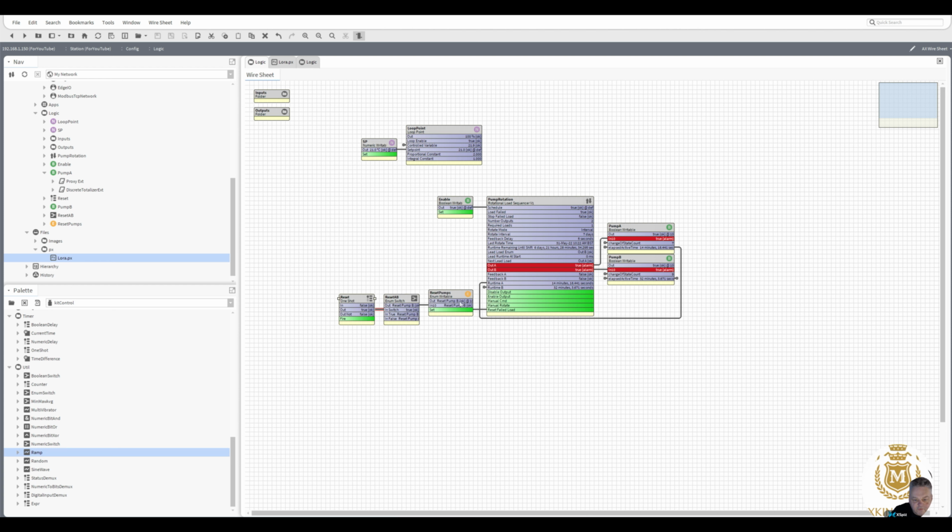So we're resetting pump B, so we're sending a 2 to that, and resetting pump A, and we're sending a 0 to that, and nothing's resetting. So we must have something wrong with our writable.